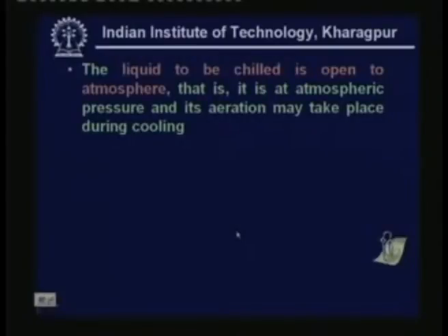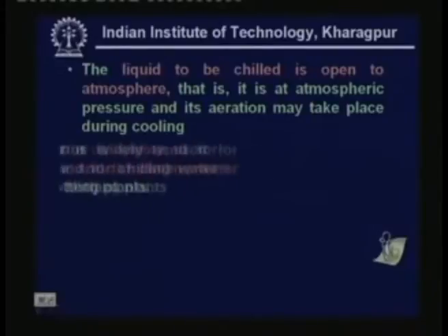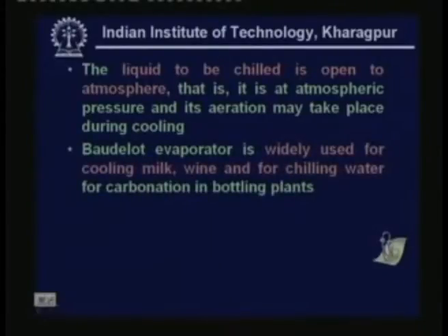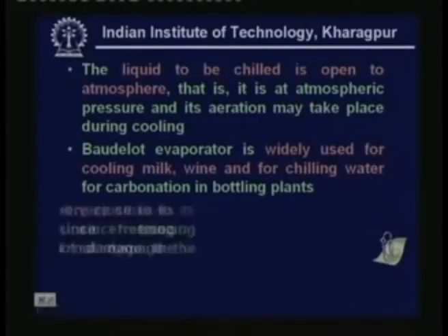So you can see that the liquid to be chilled is open to atmosphere. That means it is at atmospheric pressure, hence its aeration may take place during cooling. Baudelot evaporator is widely used for cooling milk or cooling wine and for chilling water for carbonation in bottling plants.